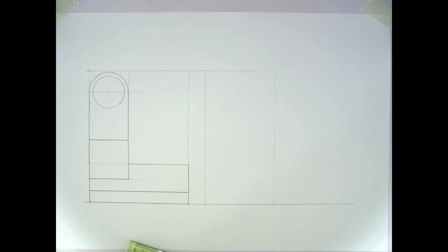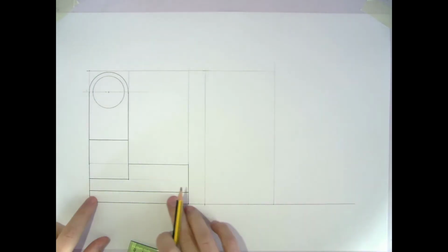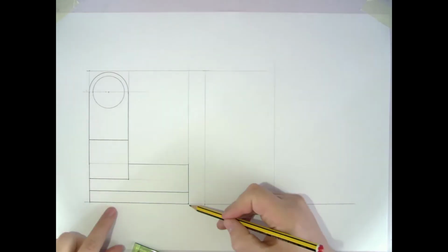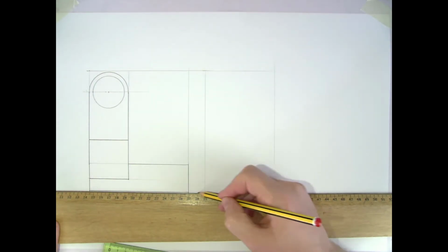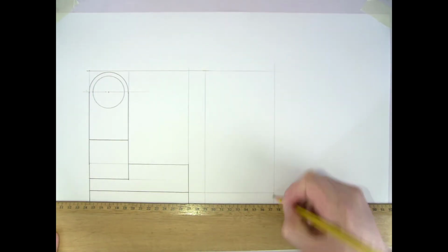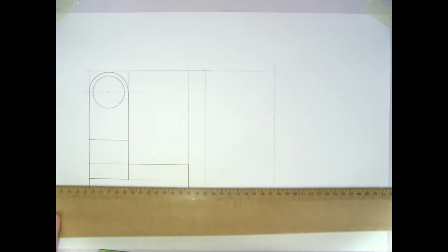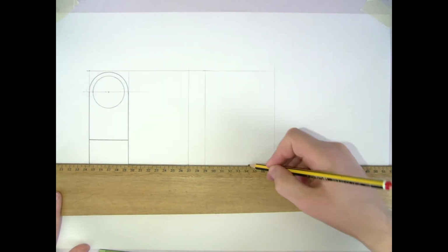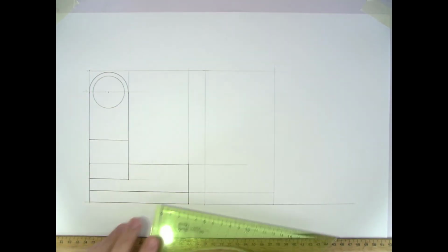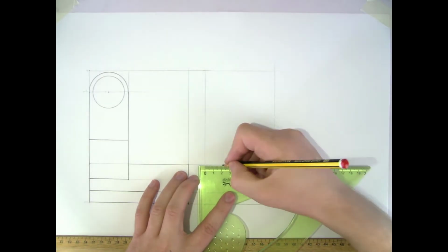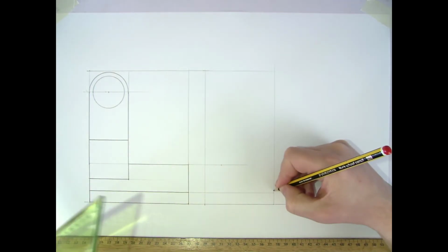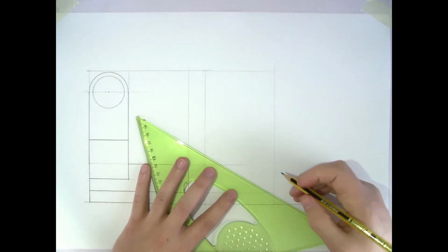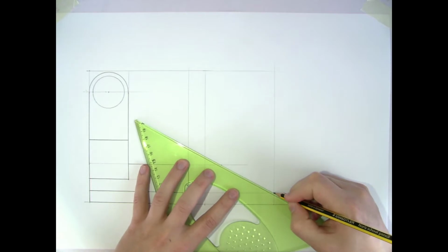So now if we have a look at the end view, we can take all of our heights straight across. So this height here is up 15 millimeters. I can just project the height of that directly across. That gives me this point here at the front. Do the same thing for the height of this up on top. That's going to come across, and I need to measure out 20 millimeters to that point there, and that's going to be coming down along this way. So I can draw that in lightly. Draw all your lines in lightly to start off with, until we know how different things interact.